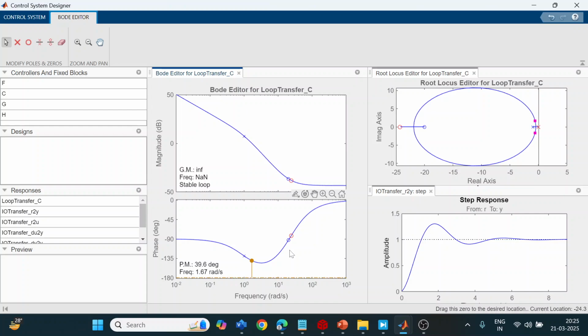Otherwise, what people do whenever they design any closed loop control is the hit and trial method, tuning KP, KI or other values. But if you have a system and you know the plant transfer function, then you can design your own compensator and KP and KI values, and put those KP, KI values in your closed loop control as the initial values.